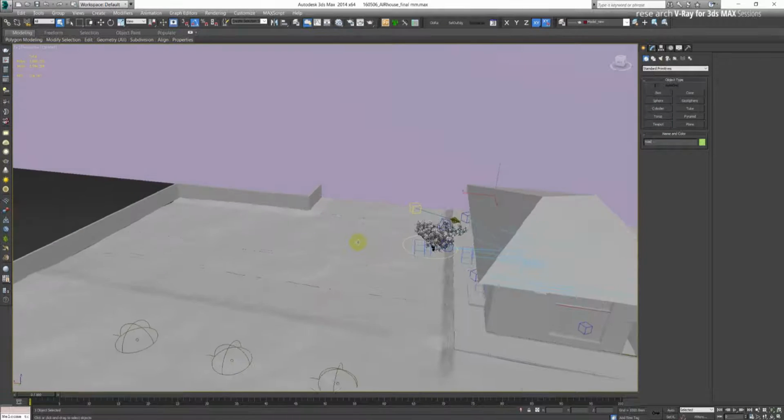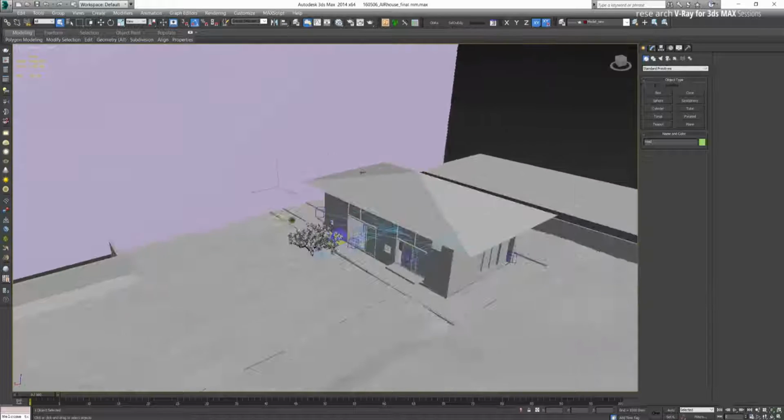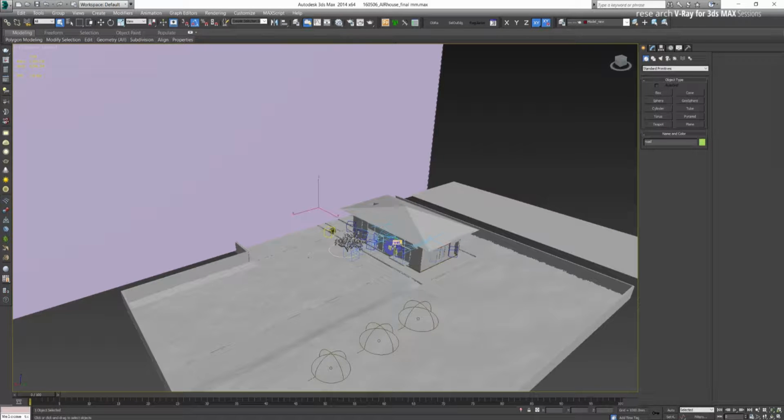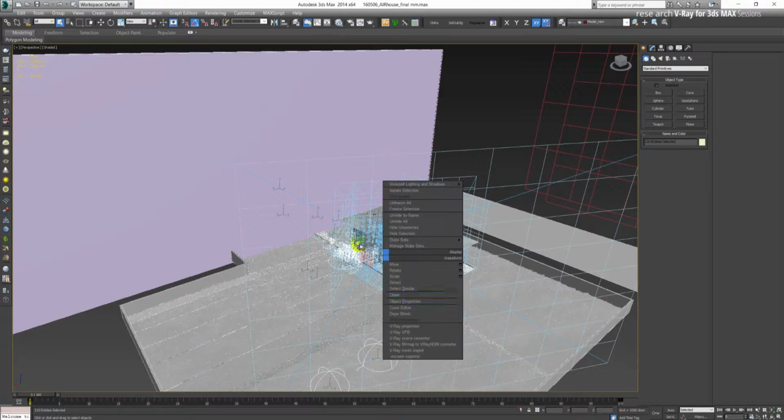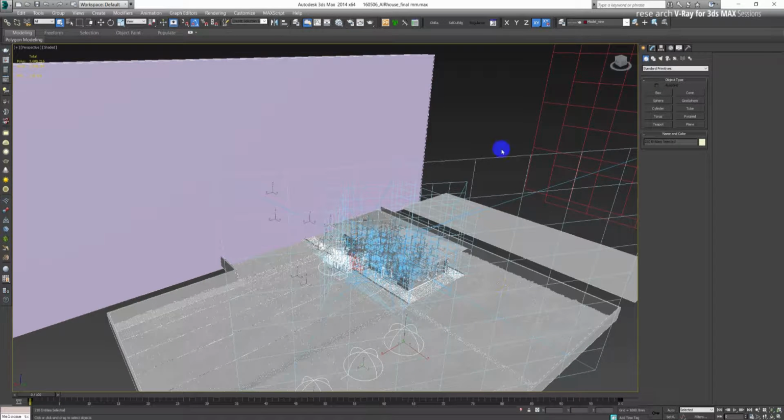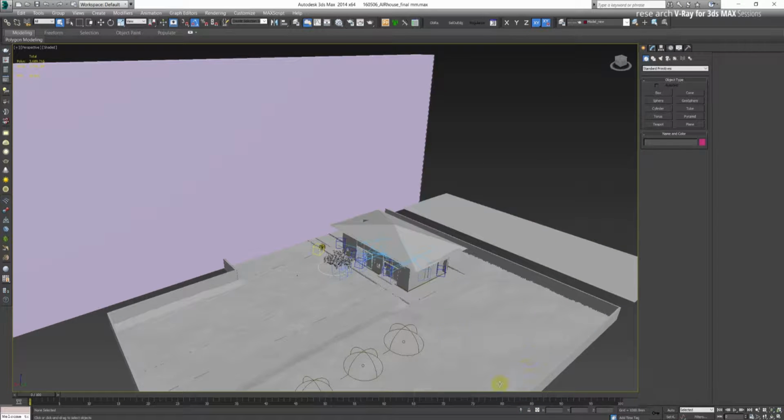Okay, so I'm back to my millimeter scene, and this you can do actually when you are done with the modeling and you just realize that you have a bigger environment than you originally thought, so you need meters. So you can take all your scene and just simply collapse it, or you can convert it all together to poly, but I have selected also the cameras.